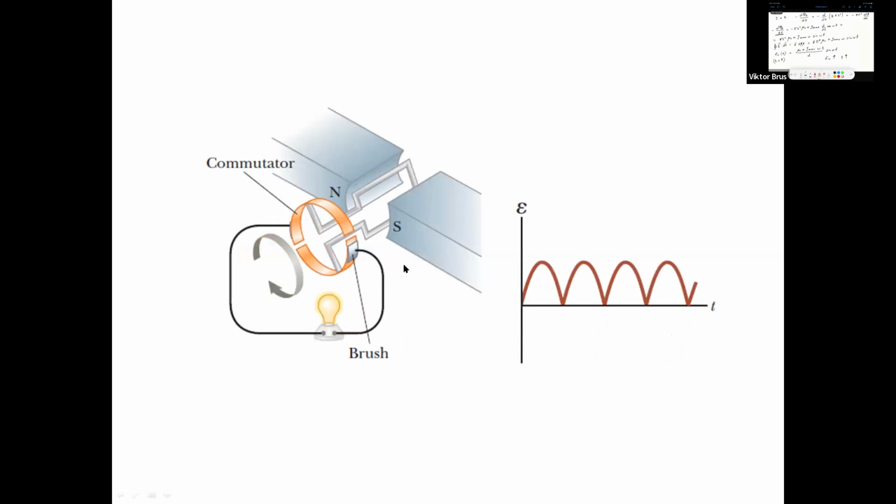If these current collecting rings are modified, so that it is called a commutator, so that at a certain moment of time you can collect induced current or get induced electromotive force only from one of the isolated semicircles of these collecting rings, then by modifying the collector as shown in the image, consisting of two halves isolated from each other, we can go from an alternating current generator to a DC generator.